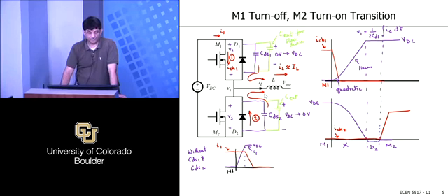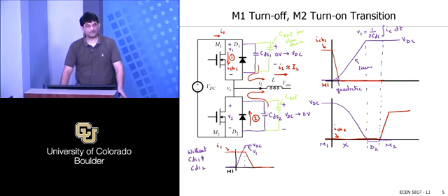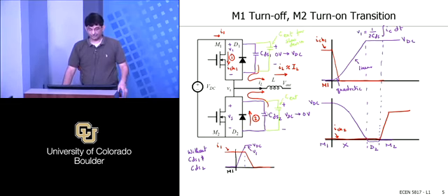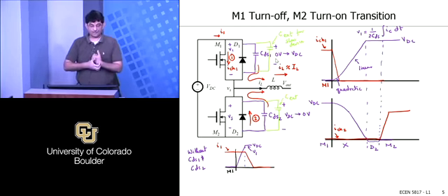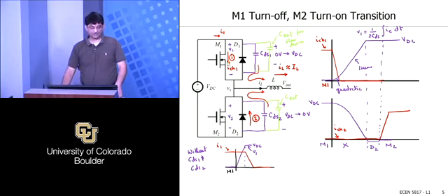We were just using the output capacitances of the devices. And if the device was slow, like an IGBT, and we wanted the same kind of transition, we could just add more capacitance. It was really a game between how fast the channel of the device can turn off versus how big the capacitor was.